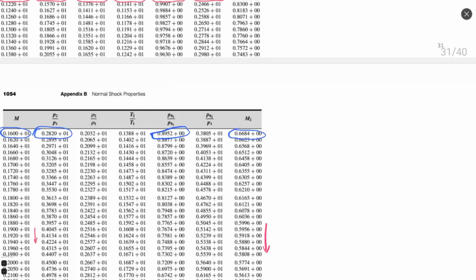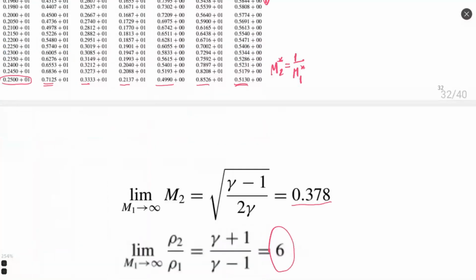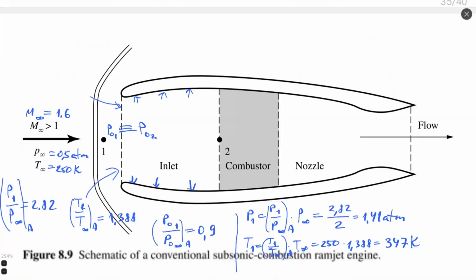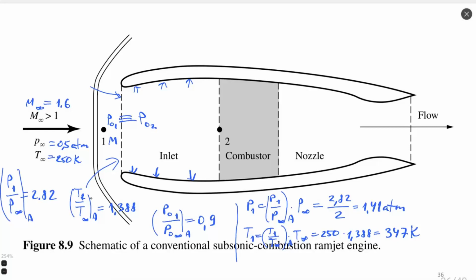It's 0.67 approximately. So here M1 is 0.67. You can see it. It's compressible, right? It's compressible, but it's much smaller than 1. So this kind of transition to supersonic velocity inside the diffuser will never happen.